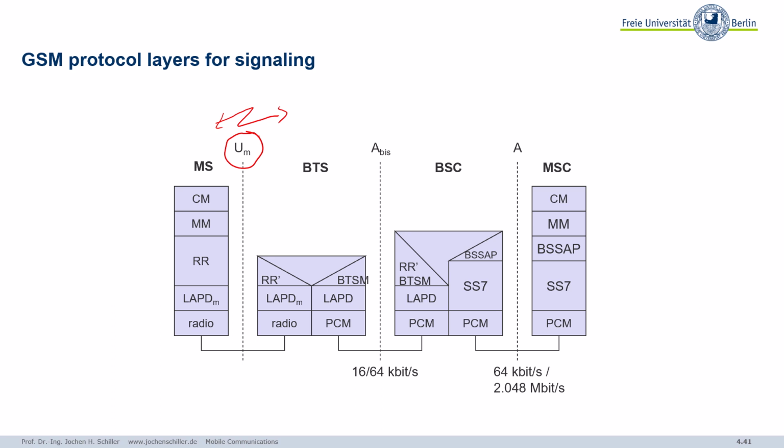And what you see there is the classical layered architecture of communication protocols where you have classical systems, pulse code modulation on the physical layer. That's what we also use in ISDN. That's for coding our typical 64 kilobit per second, 8-bit per sample or 7-bit per sample voice, for example. Then we have the classical signaling system SS7. That's the signaling system used to connect the databases to forward numbers and all this.